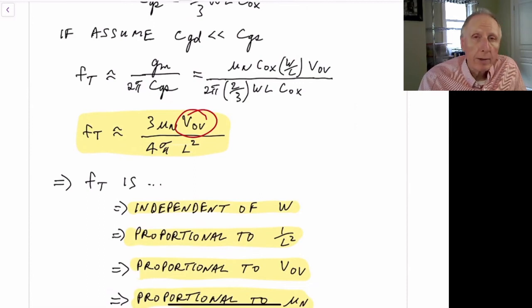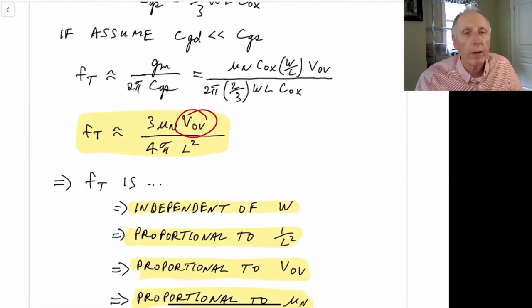You actually find this in digital circuits as well. If you have some digital circuits that operate with a width equal to, let's say, 1 micron, and then you double all the widths throughout the circuit to be 2 microns, the circuit doesn't run any faster, assuming there are no parasitic or wiring capacitances that we're taking into account. We were just driving other transistors, and all the other transistors are scaled equally.